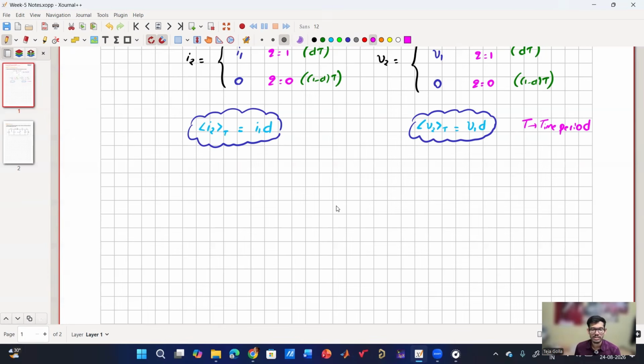That perturbation, which we represent using tilde, will eventually be used to get the small signal transfer functions, and the DC value that we are considering will let us know the DC analysis. So the circuit will have two things: one is the DC value, one is the small signal AC value. Using DC, we can perform DC analysis to find the operating point.